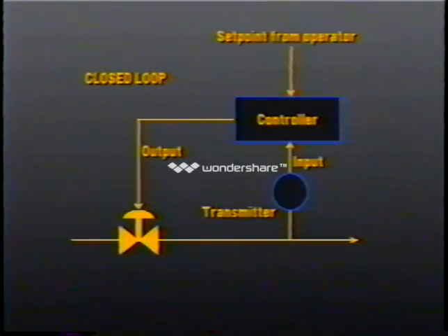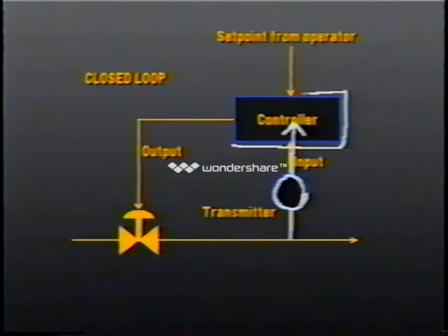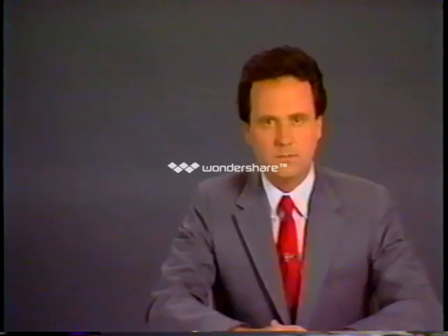Closed-loop control generally means that the process output or controlled variable is measured and then, by means of a feedback loop, is used to form the basis of calculations within a controller to determine the change in input necessary to keep the process within its desired operating parameters.